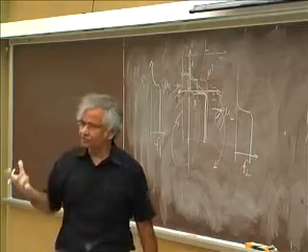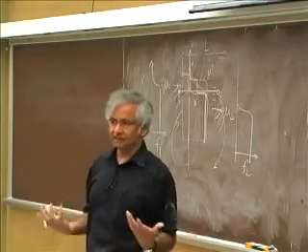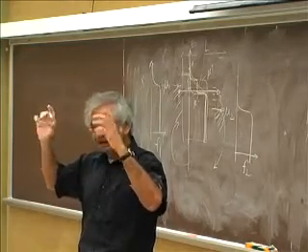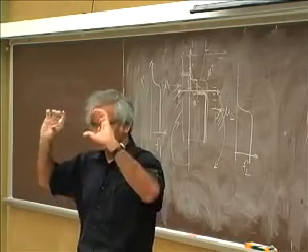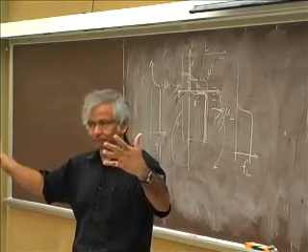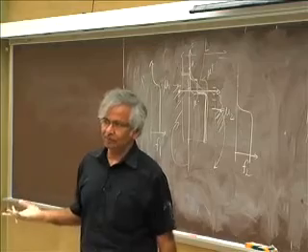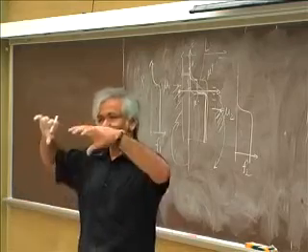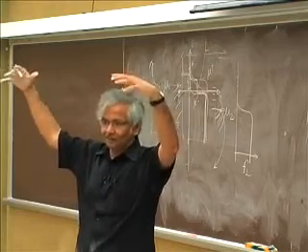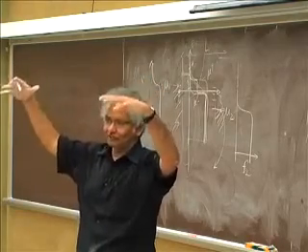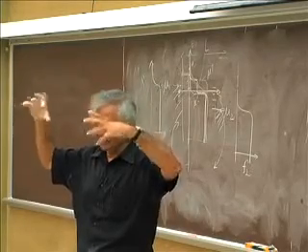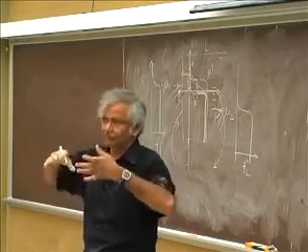Now the point you are making is true: in nanoscale devices, one can argue whether your source and drain regions are acting as good contacts. Are they really able to maintain F1 and F2, or can they get depleted? Conceptually that is quite possible, in which case you should think of them also as part of the device, and the real contact being somewhere else, where you actually have the solder, the blob outside. That's the real contact. And the source and drain are also part of the device that can go somewhat out of equilibrium.